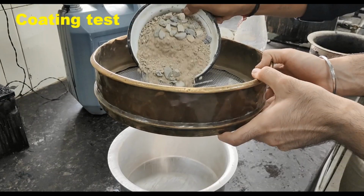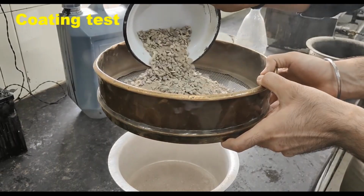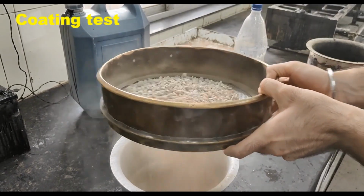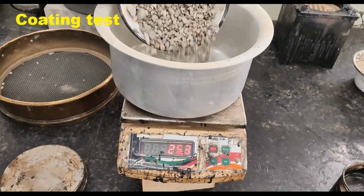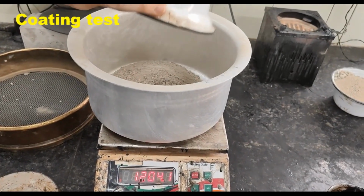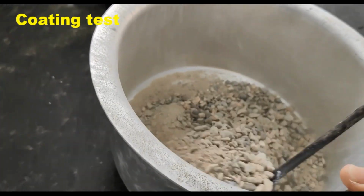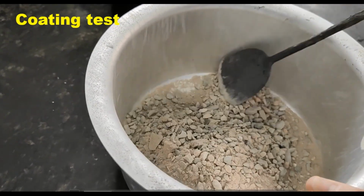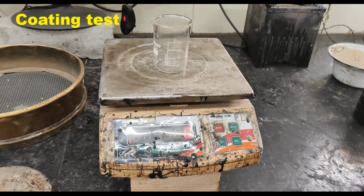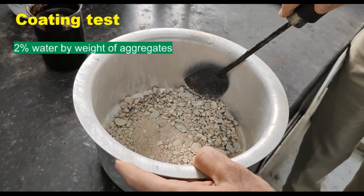Dry the aggregate in the air so that each size is easily separable. Particularly, fine material passing 4.75 millimeter should be free flowing. Determine the moisture content of air dried aggregate. Take 1200 gram of air dried aggregate as per grading of the mix, for example, BC in this case. Place the aggregate in a bowl and add predetermined percentage of water. This water is taken as percentage of dry weight of aggregate, but it is added in excess of the air dried aggregate.